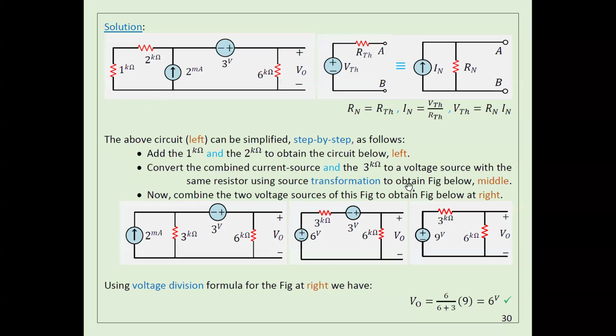So what happened here? Yeah, we have a resistance in the middle here. Because they are in series, I can just move this one here. Okay. So now, if you look at what I did here, for sure the solution will be much easier than if you use the original circuit to calculate the voltage. Okay, so here it will be very, very quick. So now, how can you get the voltage here?